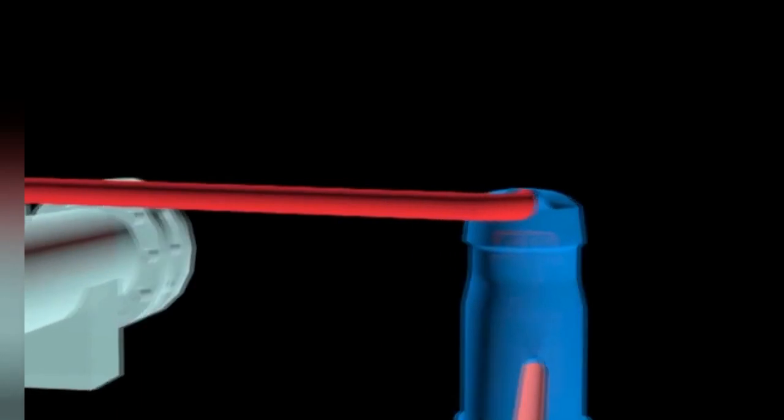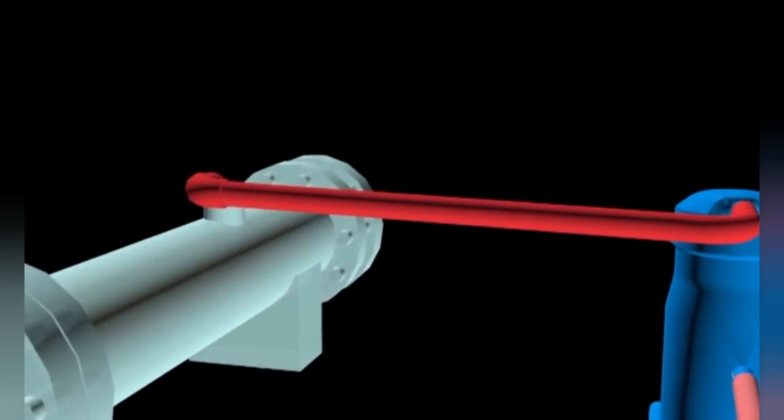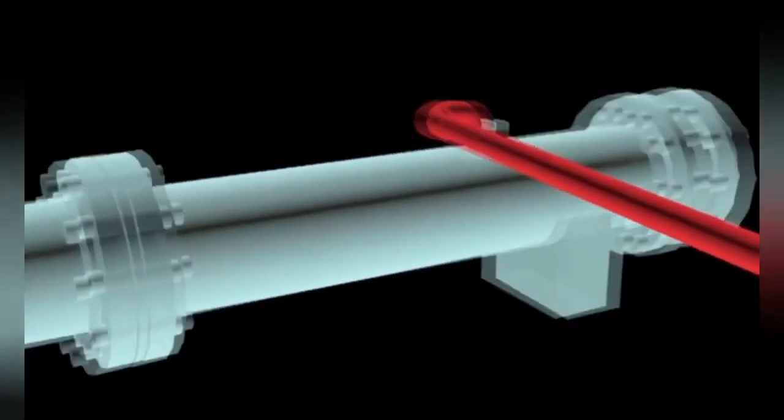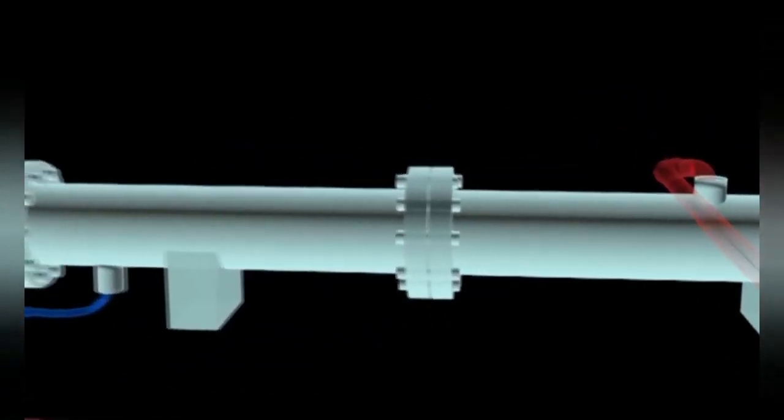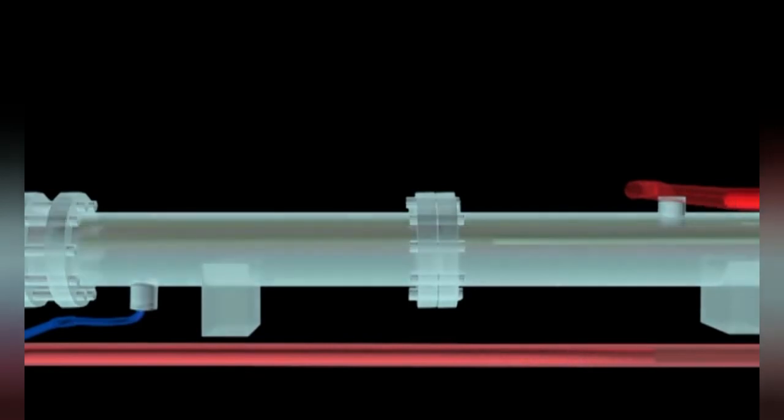Condenser. The refrigerant in high-pressure gas enters the condenser at a temperature higher than the temperature of the condenser water. In the condenser, the heat is eliminated to the condenser water from the cooling tower through the process of convection and conduction. After the heat is removed, the refrigerant in high-pressure gas is condensed into a high-pressure liquid when leaving the condenser. The condenser most commonly used is the shell and tube type. Water flows through the tube while refrigerant liquid is flooded in the shell.